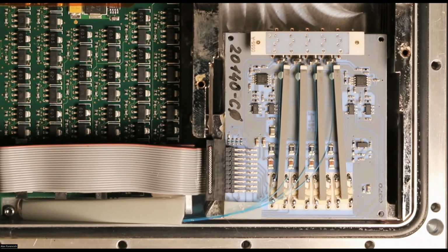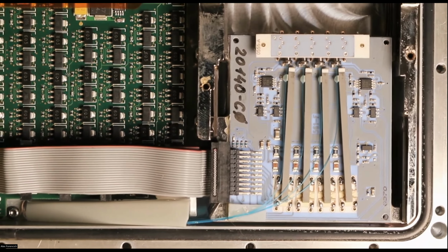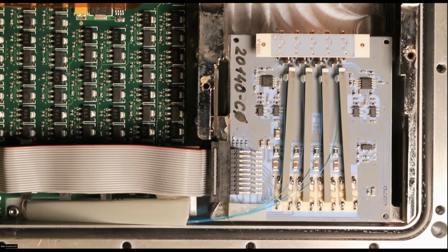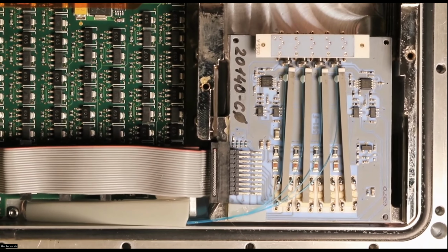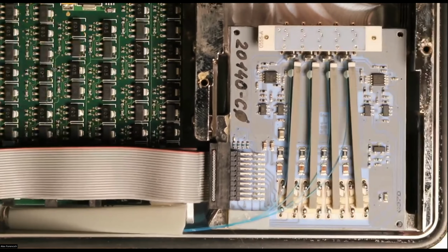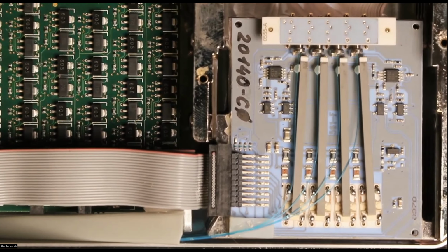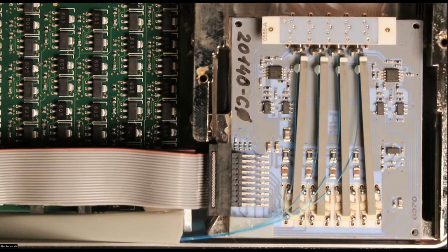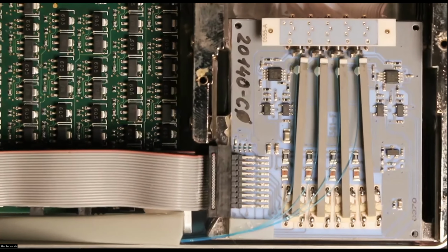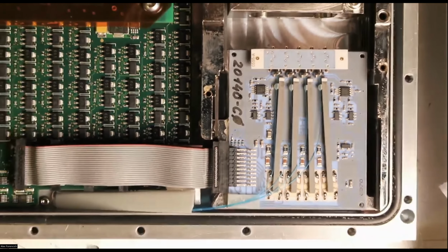The other thing I noticed as well is that I thought this was a single mode switch, but after getting the fibers cleaved and put into a couple of fiber adapters, they appear to be multi-mode fiber. So I guess that means this is actually a multi-mode switch. So I'm not sure if it's even going to work for the single mode modules that I have, even if I do get everything working and get stuff terminated and whatnot.